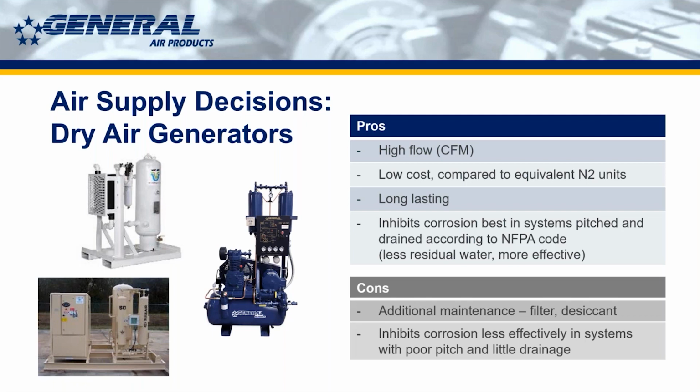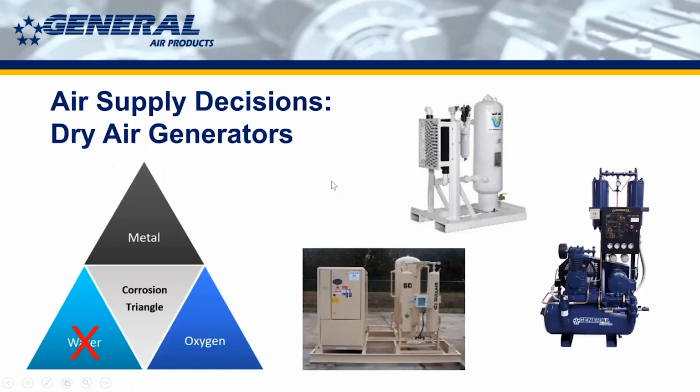So just like it's used in the military for tanks, it's used in the fire protection world. But there is additional maintenance over regular fire protection air compressors, just because this is a more complicated piece of equipment. The desiccant needs to be changed every 3 years. So that's something to keep in mind. And then there's a couple filters on there that need to be changed annually. Yep, I think that's good for that slide.